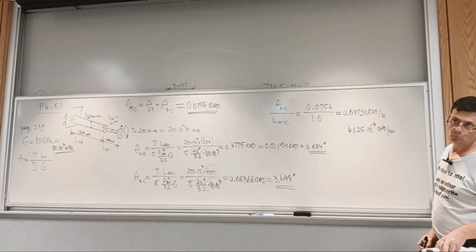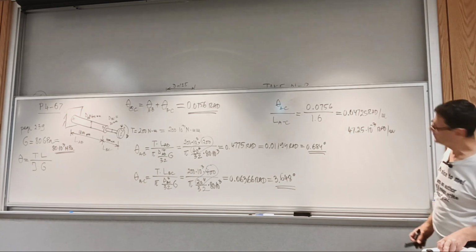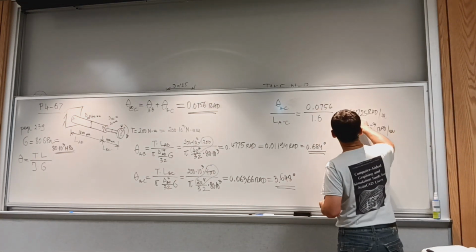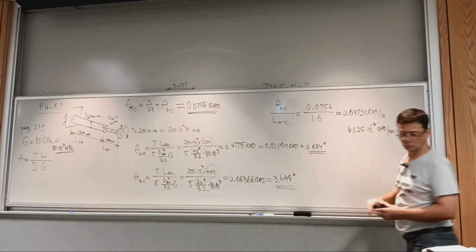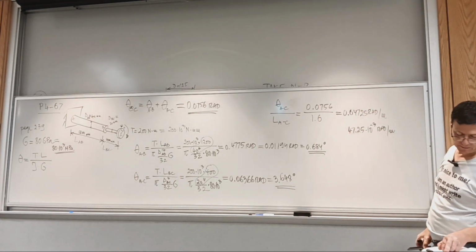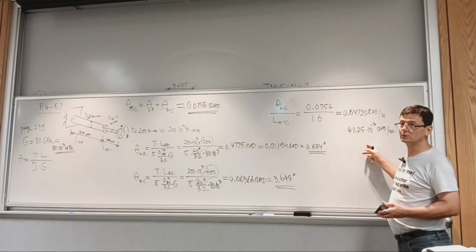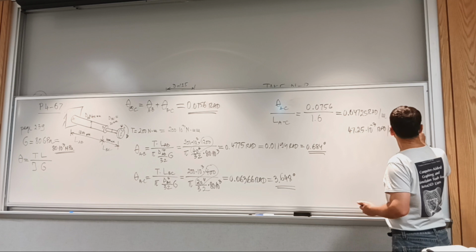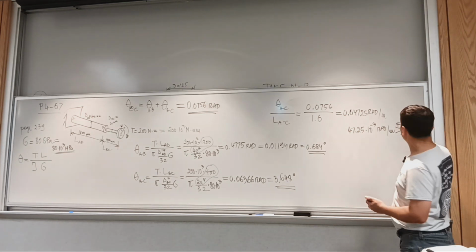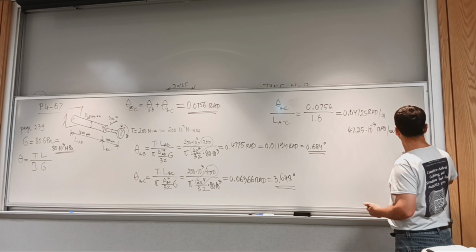So we are within the recommended, or is it? I said -1, -2, no, -3. So it's 47.25, and the maximum should be 6.9 times 10 to the negative 3. So too much twist. This is way bigger than 6.9 times 10 to the negative 4 radians per meter.